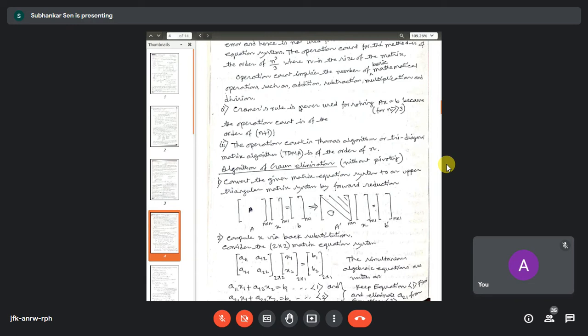Backward differencing of first order will give something known as false diffusion or numerical diffusion, or it will generate some artificial viscosity or numerical viscosity that will again contaminate your solutions. Okay, so if you follow this guideline, upwinding for the convective term, central difference for pressure gradient and viscous terms, then your matrix will be diagonal dominant for the fluid flow equations.